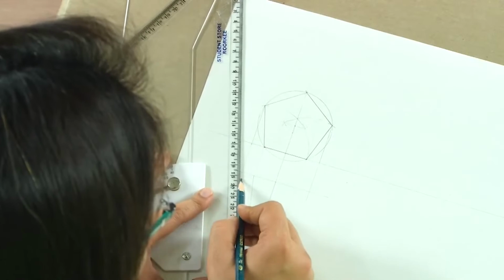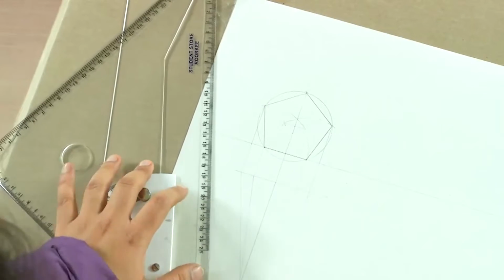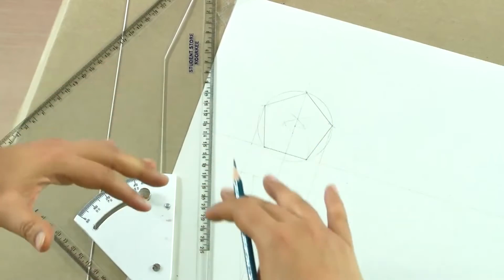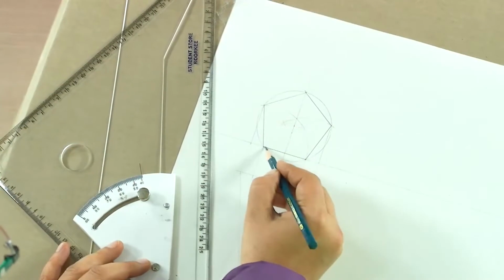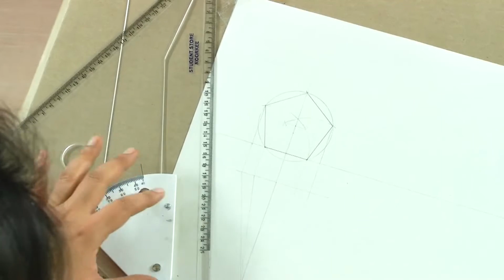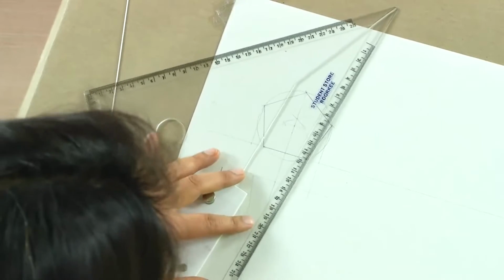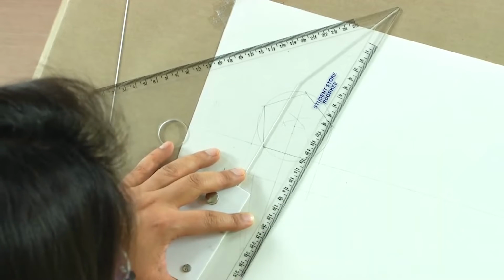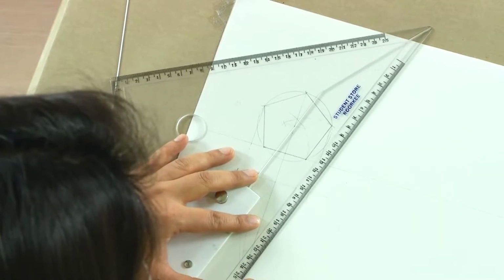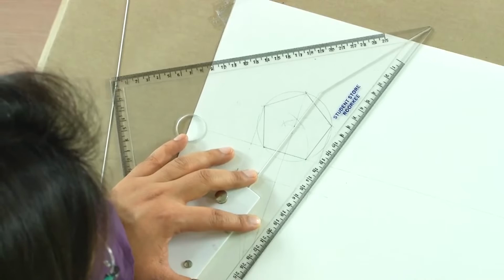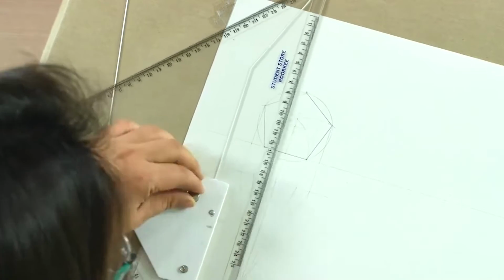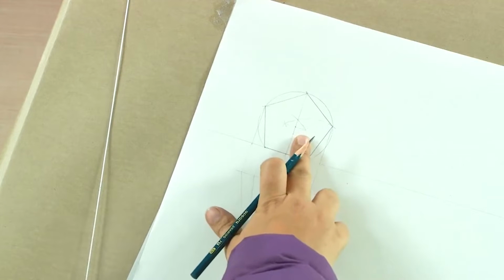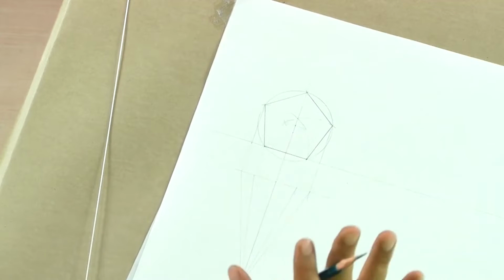Right now, I am drawing it very light because if you look at it, we will actually not be seeing this side because it is below. From the top, we will not be seeing the two sides joining these 2 points to the apex, but to facilitate an easy drawing, we will have to draw it, and hence we draw them very light. So, you have to be careful about what you draw light and what you draw dark. Now, this is the projection of this pyramid if we see it in the simple position.